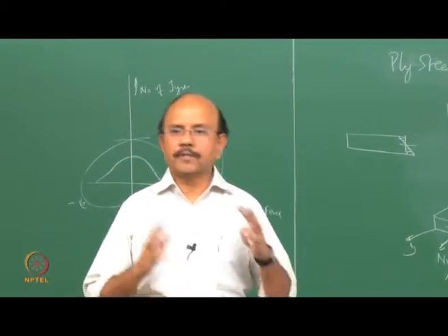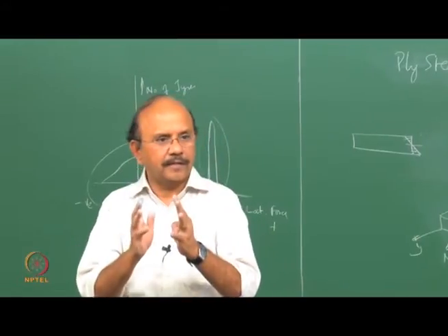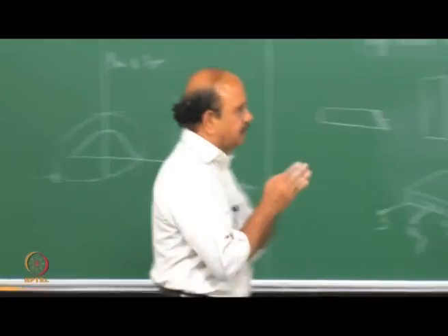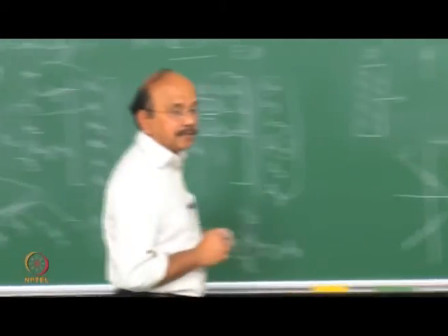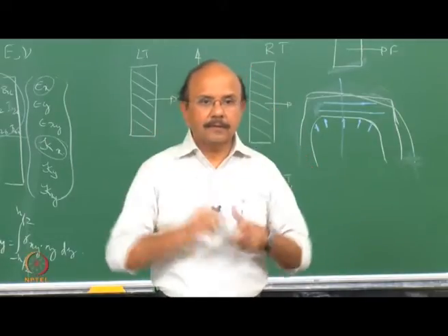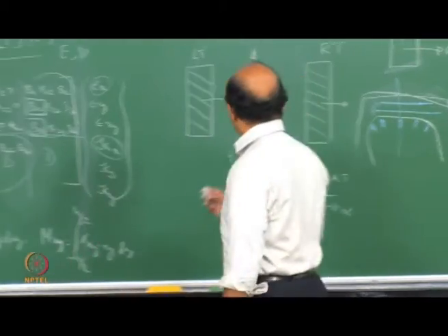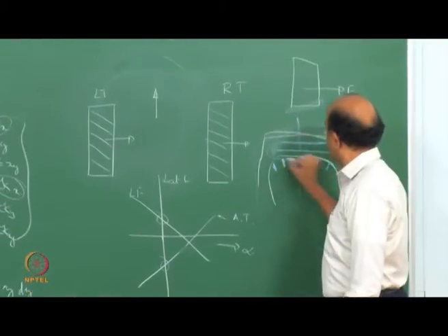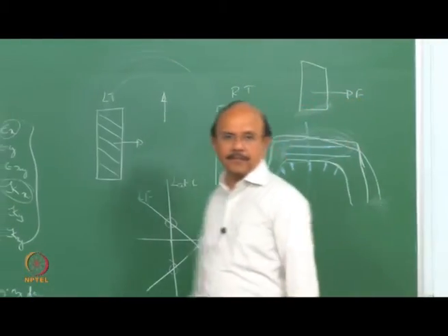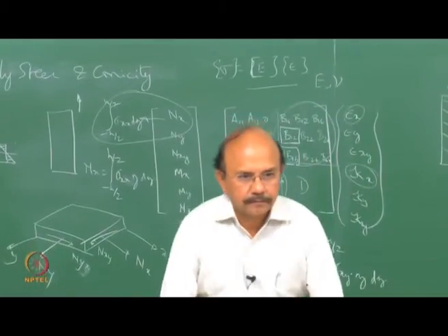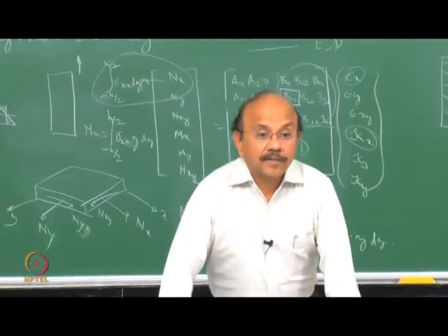In other words, is a straight running tire going to be a nice guy who runs straight, or is he going to do other magic? Is the conicity a manufacturing defect, or is it something else? Yes, it is. In most instances, it is this belt offset that causes conicity. It's a defect. Now that's not the end of the story.